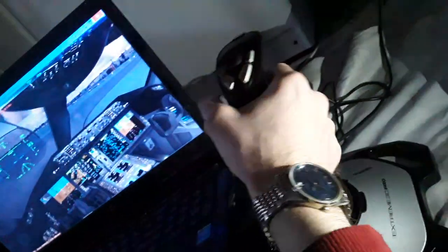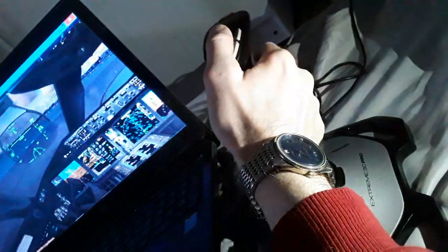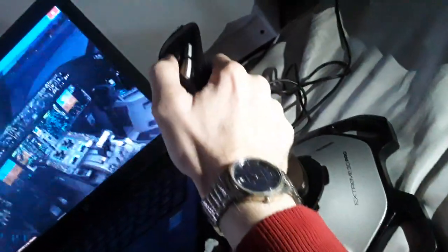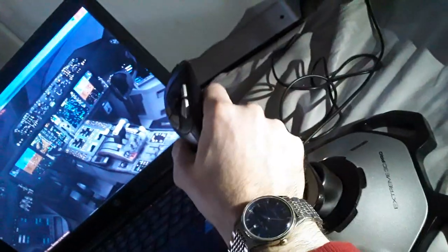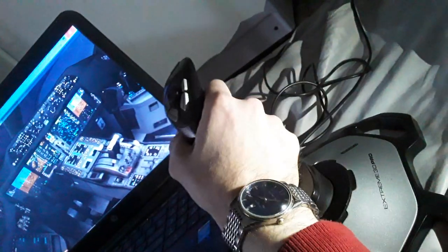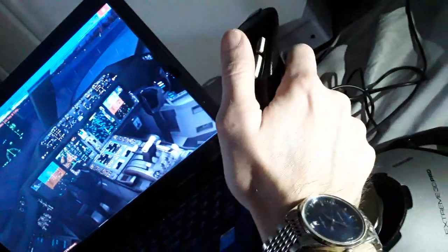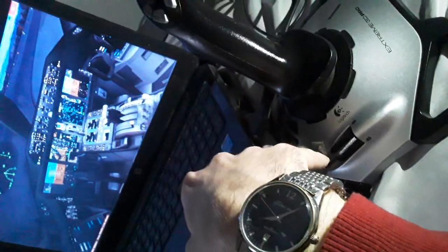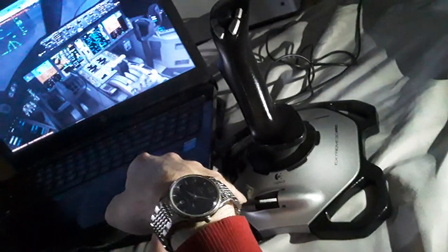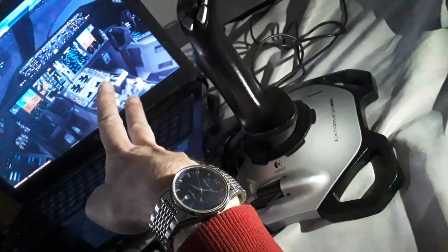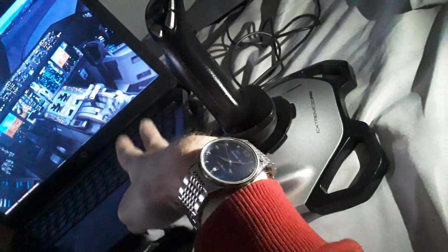So you can climb, you can descend, you can make turns to the left, turns to the right like this. So you use the pitch axis, the elevator for climb, descent. Also the side stick left and right in the Airbus is the control wheel, as you can see in the Boeing. Also the rudder pedals, the horizontal trim stabilizer, the thrust levers like this, can increase and decrease the thrust commanded to the engines over here. So you have the engines set over here.